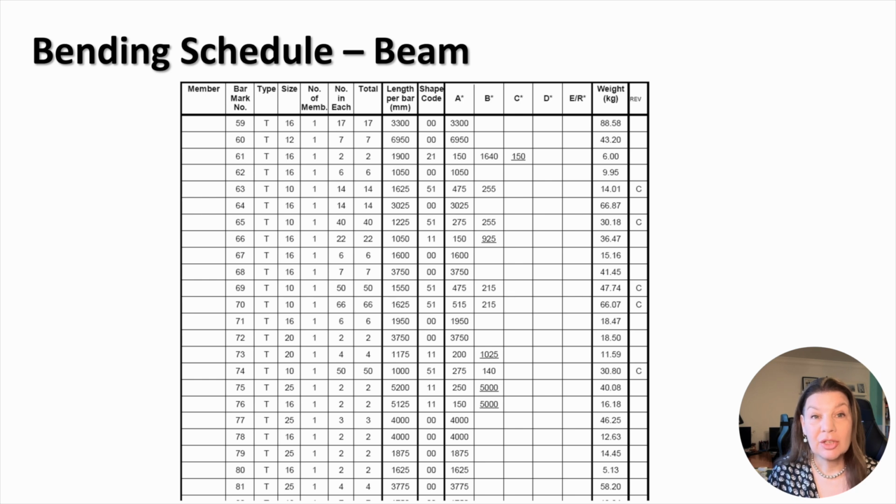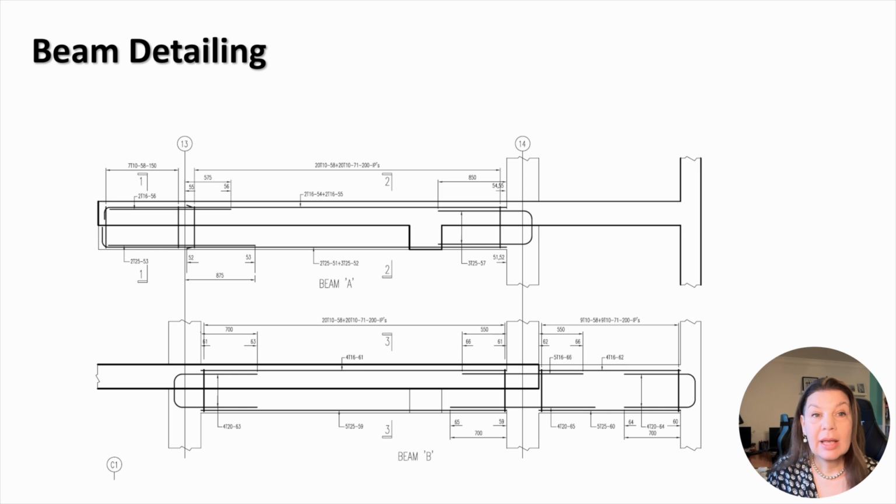This is a bar bending schedule describing necessary numbers, values of geometrical parameters, and the weight for each bar in the steelwork of a beam. This slide shows examples of reinforcement arrangement in concrete beams. As can be seen, mark, location, and number are specified for each bar.